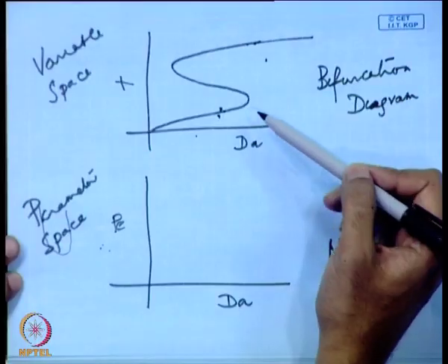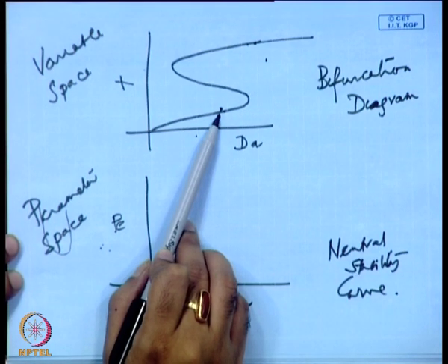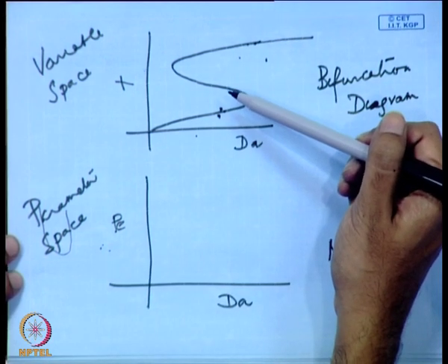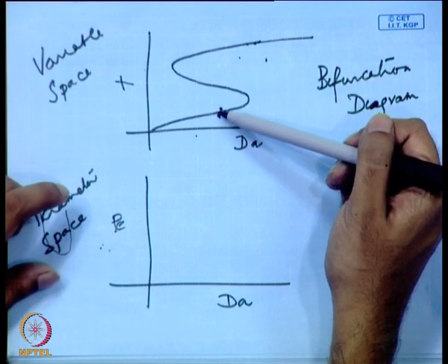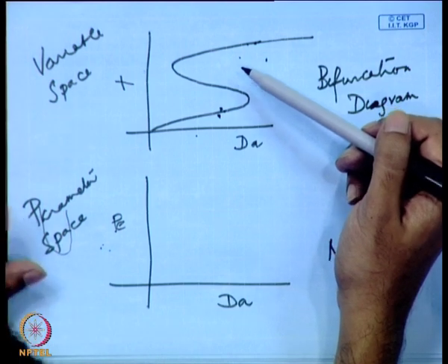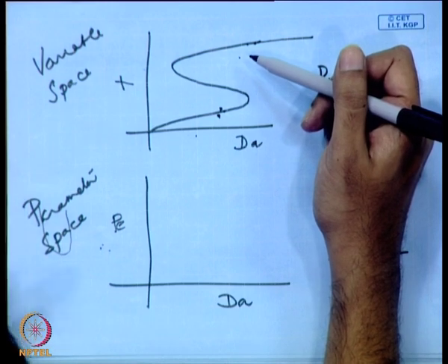The first is stability. Once the system is stable, there are two possibilities, that the system could be in the ignited branch or in the extinguished branch. If you look over here, as we discussed, the bottom leg is stable, the top leg is stable, but the middle leg is unstable. So, even when the system is stable, there is still a possibility of it being in the ignited branch or in the extinguished branch, and you want it in the ignited branch, right. I will come to how to figure that out, but your first criterion is stability.